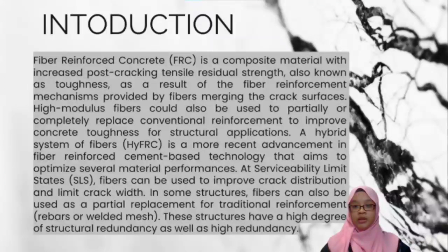At serviceability limit state, fiber can be used to improve crack distribution and limit crack width. In some structures, fiber can also be used as a partial replacement for traditional reinforcement. These structures have a higher degree of structural redundancy as well as higher redundancy.